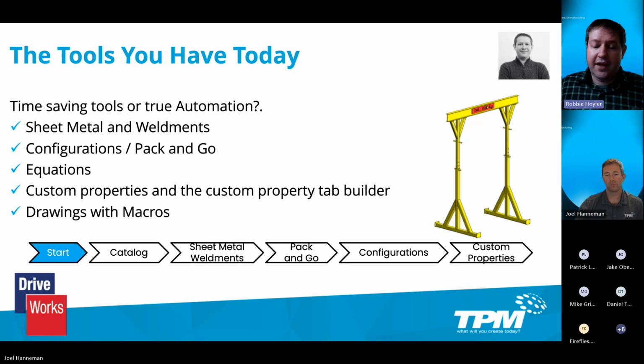And from there, you can get even deeper, right? We've got the ability to play with drawings and make them consistent with a template. And then we have macros that we can run. SolidWorks has an open API. On the highest end of this, you have macros that will do batch jobs, like automatically creating PDFs of all your drawings at the end, or generating an Excel file that needs to look a specific way. So these tools are built into SolidWorks, but it's not quite design automation. These are just time-saving tools.